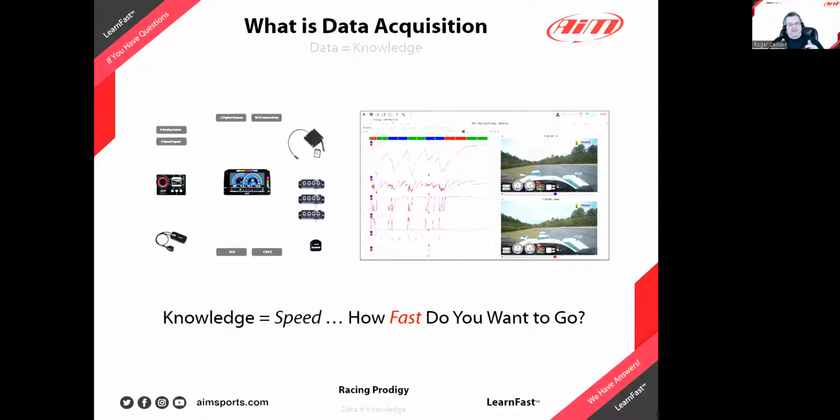Meanwhile, you come back, and I have that discussion all the time with drivers where they say the car was loose on exit, it had oversteer on exit. But what they didn't recall, because there's so much coming at them, is that the oversteer from the middle of the corner out was because of the understeer that was happening first. The first thing they recalled in their memory was the oversteer. There is just so much coming at you that we can back out of it in the data and try to understand what happened and why it happened, right?